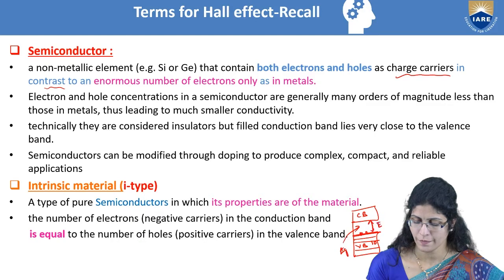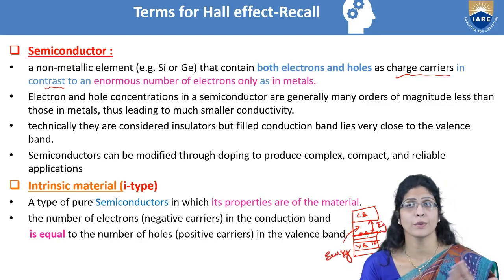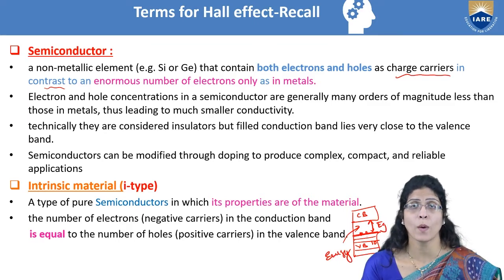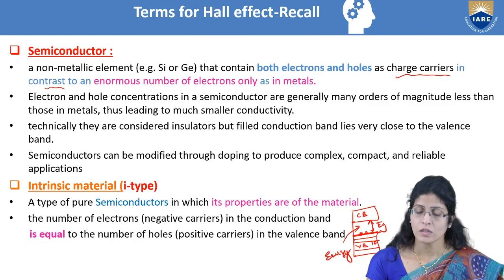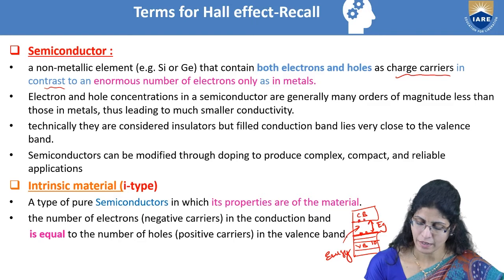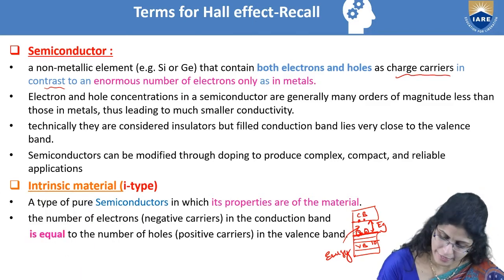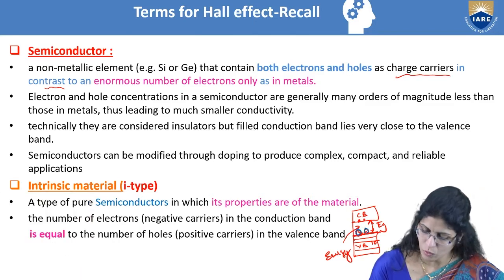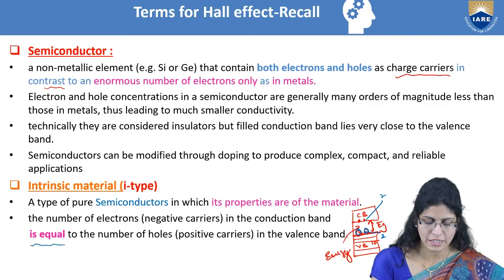It's the Eg, taking the energy you give. It may be in the form of heat. You may be providing some heat to the crystal or to the semiconductor lattice. So this will take that external energy and excite to the higher energy level, maybe here and here, leaving a vacant site here, right? So this vacant site here is known as a hole. So how many holes do you have here? 2 holes, and here you have 2 electrons. So that's what mentions equal.